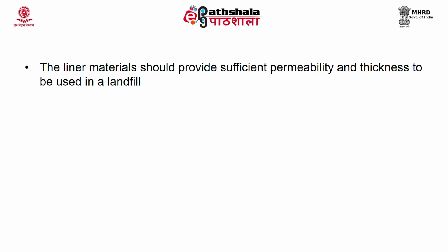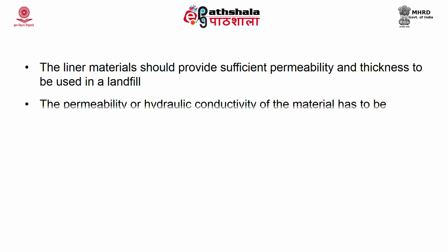The important criteria which you have to consider while selecting a liner material is its permeability, also called hydraulic conductivity. Permeability, as you all know, means how much fluid it will allow to pass through. The higher the permeability, the more you should avoid such materials, because it will allow water to pass or drain through it. So, always select materials with lower permeability.